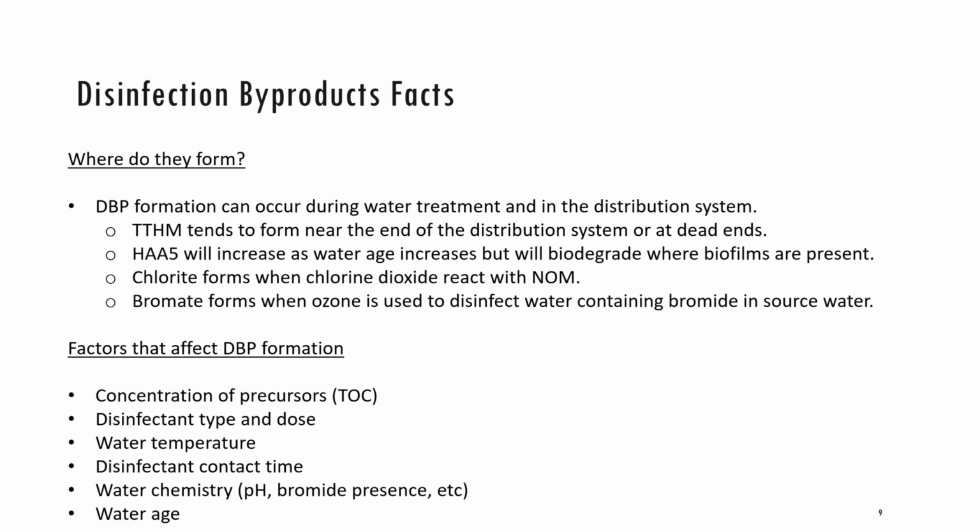These chlorine residuals are important to make sure to disinfect pathogens or microbes that are present in the distribution system. But these residuals can also react with dissolved natural organic matter in the distribution system or biofilm located in the distribution system to form DBPs.